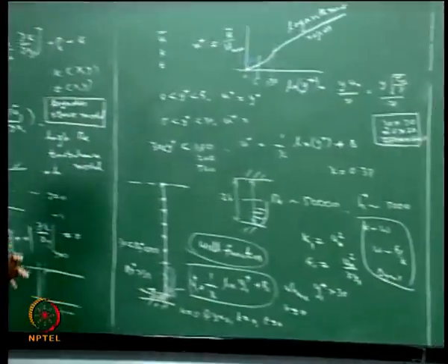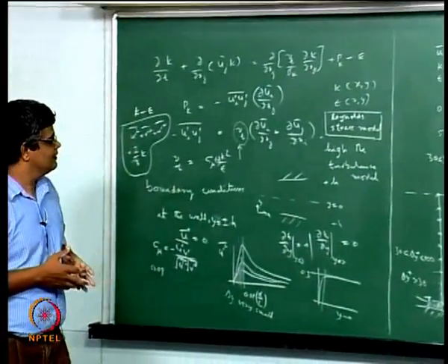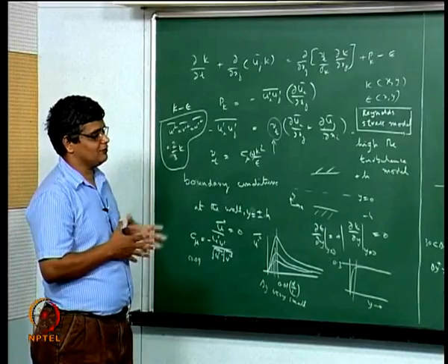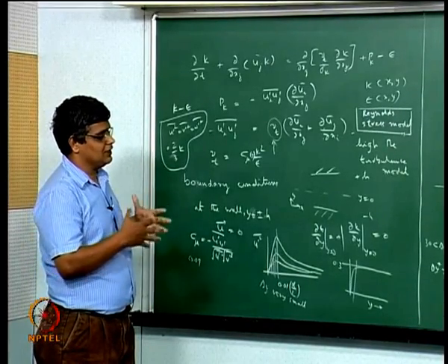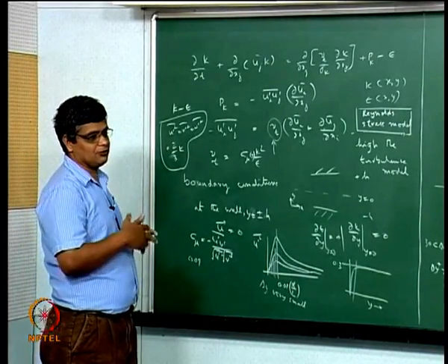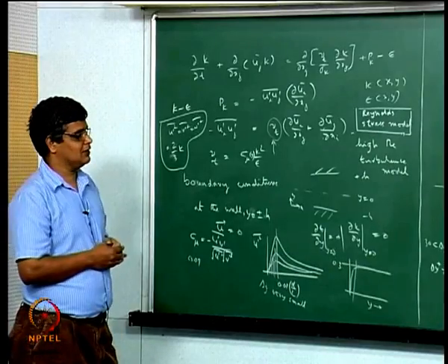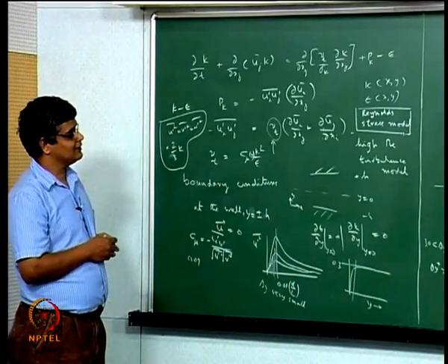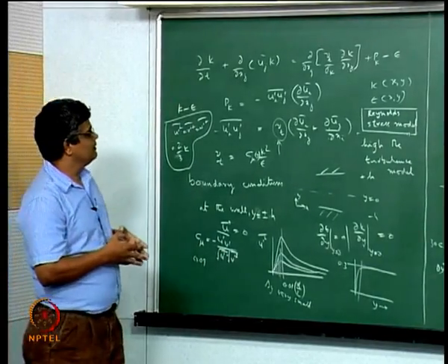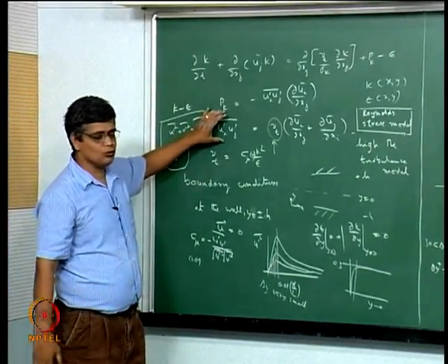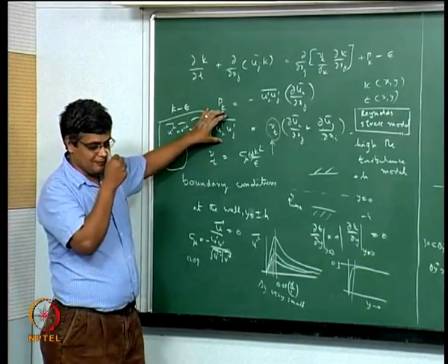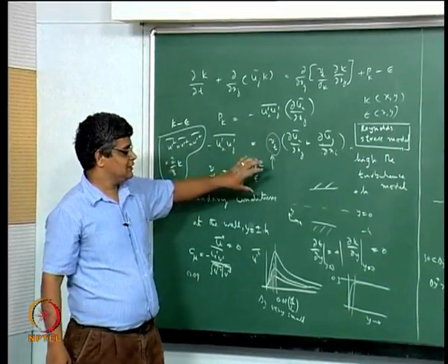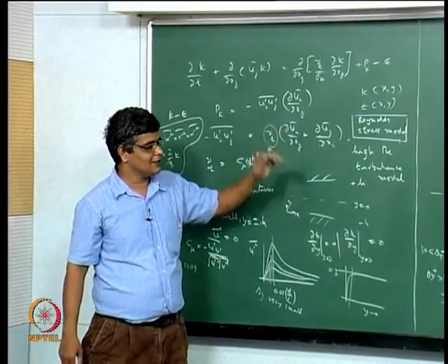One can see that in the general case we have to use some sort of Reynolds time averaging of the governing equations, so that we do not have to worry about the very fine turbulence fluctuations, temporal and spatial, but in the process we come up with additional unknown quantities like the Reynolds stresses, and these are only approximately modeled using a vast array of models.